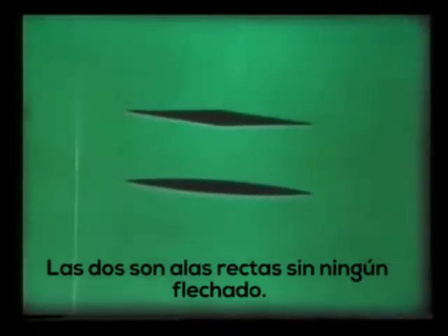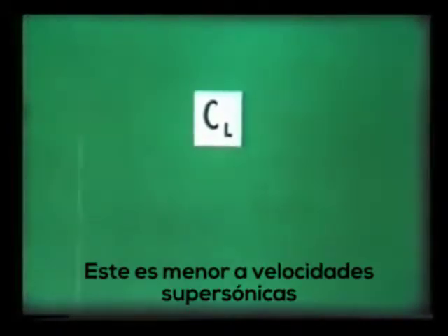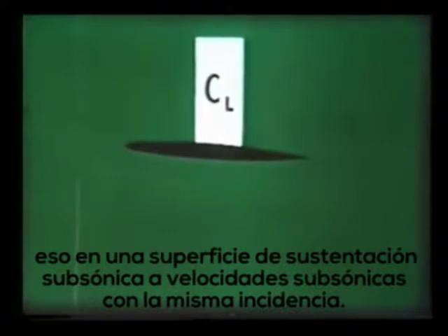They apply only to straight wings without any sweepback. At a given angle of incidence, they both have the same lift coefficient. This is smaller at supersonic speeds than that of a subsonic aerofoil at subsonic speeds at the same incidence.